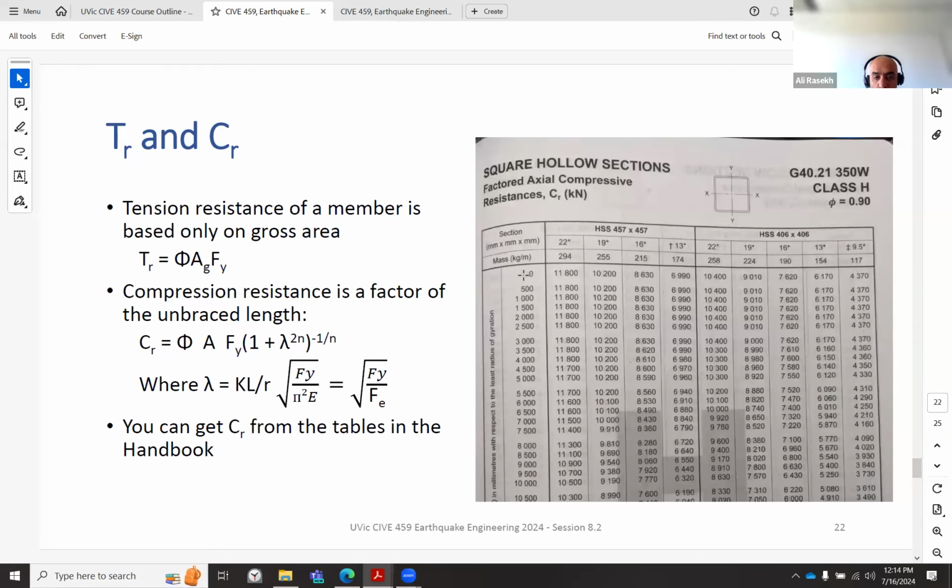And these are the different lengths, because this buckling resistance, in a way, compression resistance is length dependent. For different lengths, the code provides the capacity. The longer the length, the lower the capacity. So basically this equation is compressed or elaborated into a table.